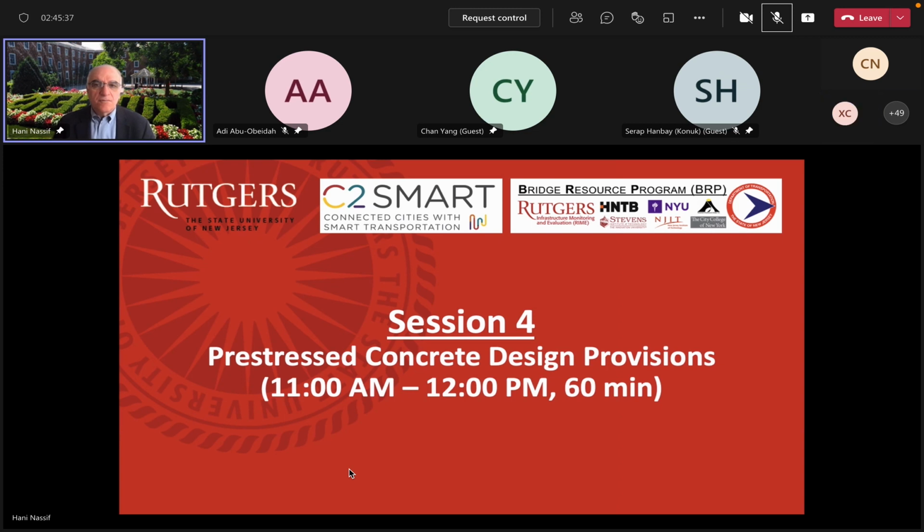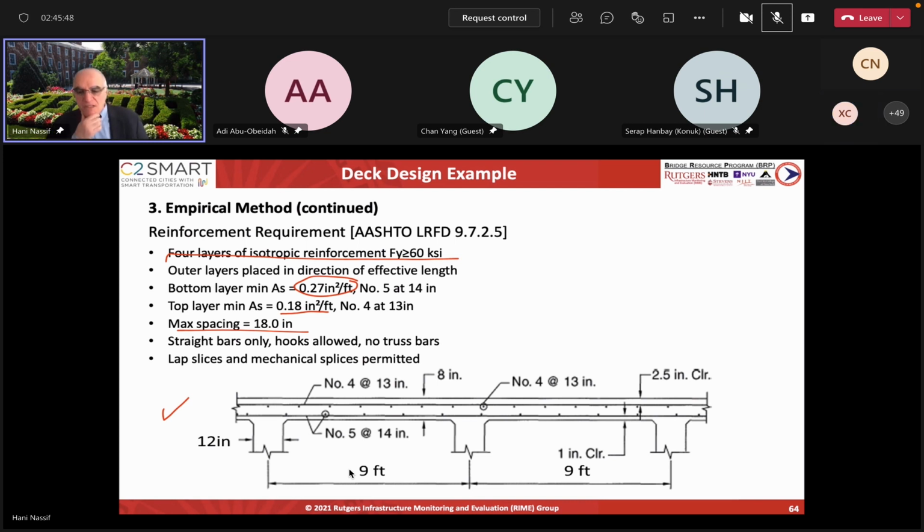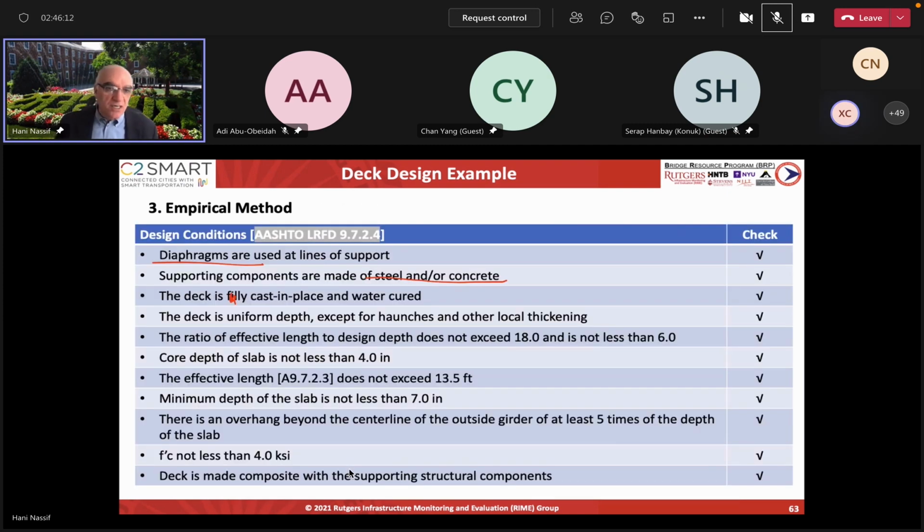Any questions? Yes. Have you ever done the comparison between these two methods? Any difference? Yeah, when we did the serviceability analysis with my student at the time, Dan Stu, we have 2 papers on the empirical method, and we found out that the reliability of the empirical method is lower because the reinforcement that you end up getting is less than what the other method provides. I have to admit, this is quicker, but it's not better in terms of design.